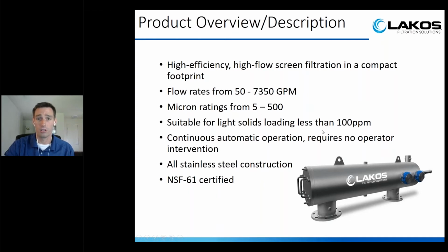It is important to note that these are meant for light to medium solids loading. If you have very, very dirty water, we would probably steer you towards something like a sand media filter instead. Otherwise, these may get overwhelmed prematurely and backwash too much.